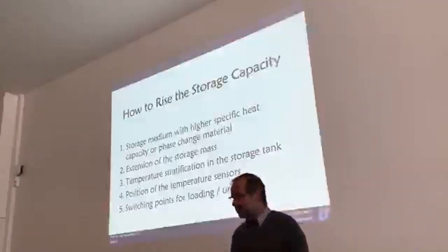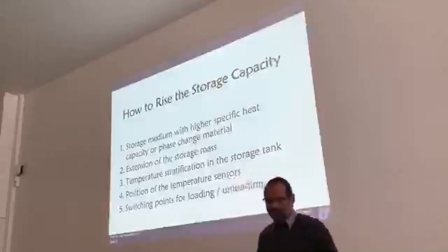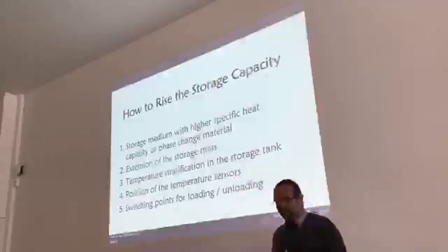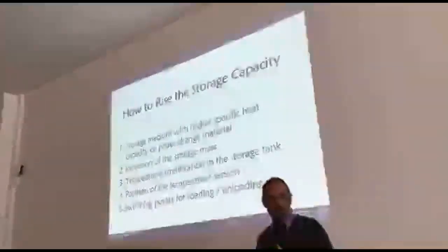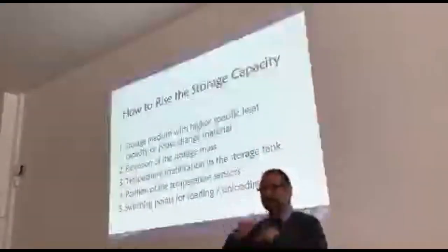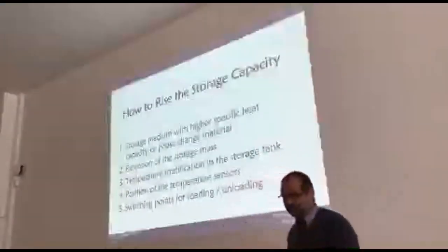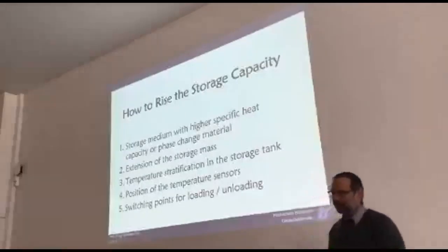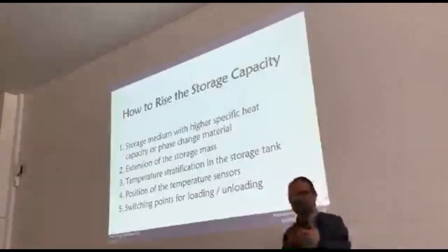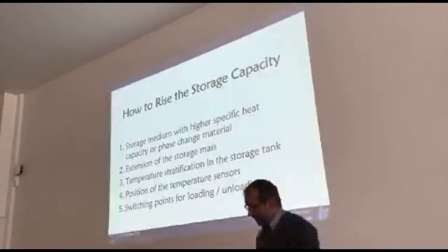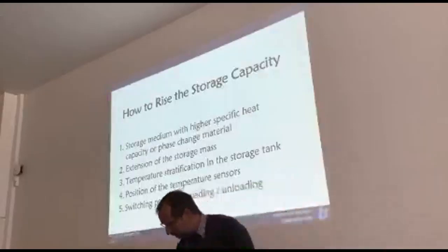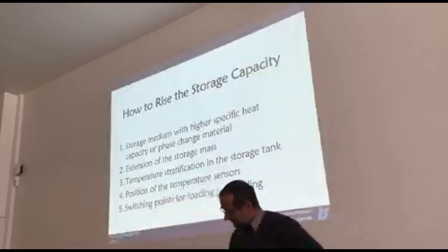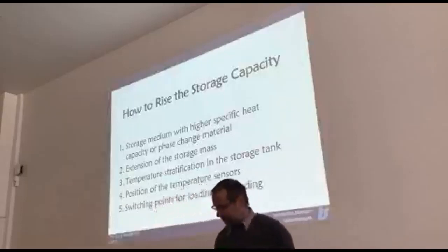Because it doesn't make the system more efficient. And we want a more efficient system, so we looked at the temperature stratification in the storage tank. That means how stable the temperatures are in different layers, how big the mixing is. We looked at the position of the temperature sensors, and we had a look at the switching points for starting, loading and unloading.